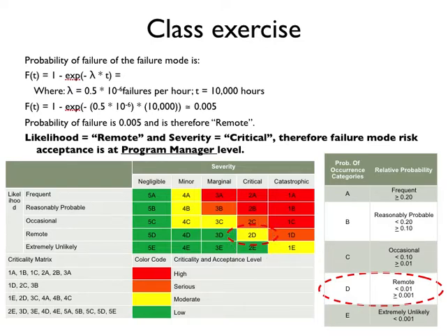So this is the step that you would take with each failure mode. And in this case, we have the actual failure rate, which is nice. We have the time value. Those are some things that we need to have in order to determine that risk. But sometimes we don't have that information. So sometimes the actual assessment gets a little bit more uncertain. And that's why we have things like the definitions that go with this table, which I showed a few slides back. We can use words like remote or occasional to better fine-tune our estimate of the likelihood if we don't have the data, right?